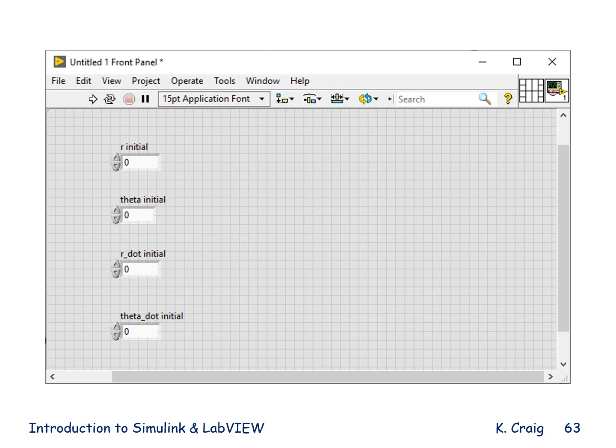Here is my front panel. On the front panel, I've inserted 4 numerical controls, one for each initial condition for my 4 integrators. The reason I do that is so that I can change the initial conditions on my front panel without having to go back into the block diagram programming to change those values.